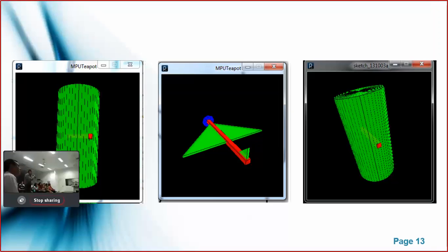We use the MPU 6050 IMU to determine the angular velocity in the three axes x, y, and z, to determine if the recovery system is stable enough or not, and by small calculation it can be used to determine the direction of the wind around the CANSAT.